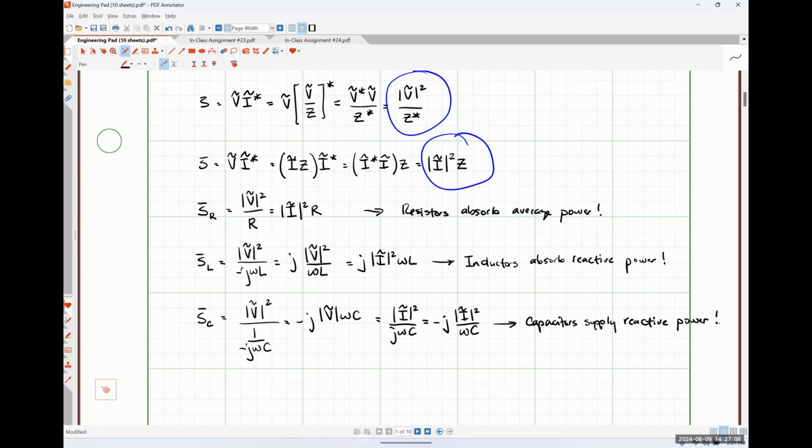So that is specifically why on the utility grid, when we introduce temporary energy storage in order to help particular systems ride out the possibility of a blackout, so near large scale manufacturing installations and stuff like that, we use what's called static VAR capacitor banks, because these guys literally supply reactive power into the system in order to regulate the voltage so that a blackout or brownout doesn't occur. Okay. We're going to talk a little bit more about adding capacitances into systems in a few minutes when we talk about power factor correction.